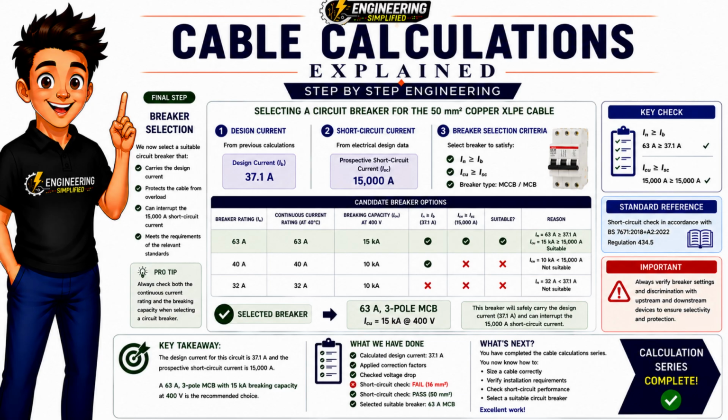A 40 amp breaker carries the current, but its 10 kiloamp breaking capacity is lower than the required 15 kiloamps. Finally, a 63 amp breaker has a rated current above our design current and a 15 kiloamp breaking capacity, exactly matching the fault level. This means the 63 amp 3-pole MCB satisfies all of our design requirements and is the correct choice for this installation.